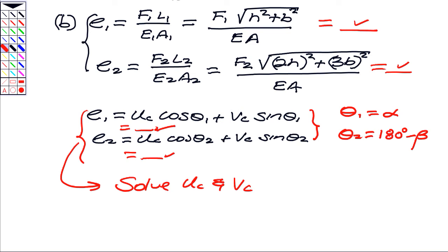From that, we used our elongation equations to find the elongation of each one, and then using the compatibility equations, we were able to solve for the displacement of that node there of C. Had the problem been indeterminate, we would still have the same steps, except we would have to solve all these equations simultaneously rather than the sequential way that we did here.